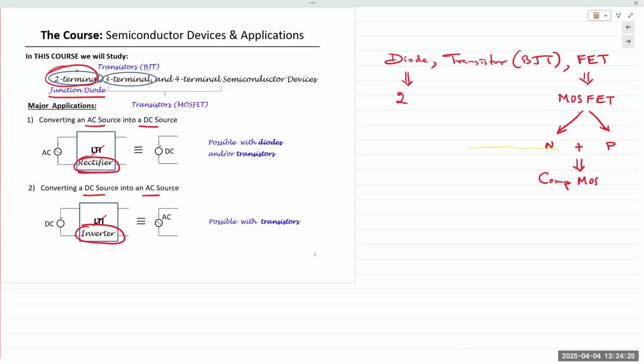You have studied inverters, logic inverters, maybe not. This is the same English word, but a completely different device. That is a logic inverter, a NOT gate, meaning you give an input, it inverts it to the output. This inverter is basically related to power. So in power electronics, DC is converted to AC. This circuit, where have you seen an application of this? Battery backup, yes.